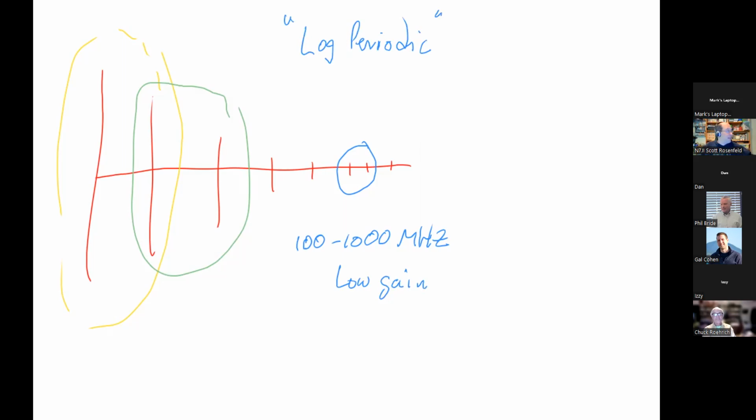You can actually do a high frequency log periodic that covers the entire 3 to 30 megahertz band, or let's say 2 to 40 megahertz band continuously with low gain, but with directivity, because you put it on a tower and it's rotatable. But something like this would potentially have so much aluminum that it would weigh a couple hundred pounds and cost, oh, I don't know, $10,000.